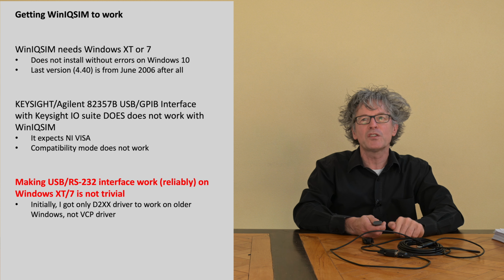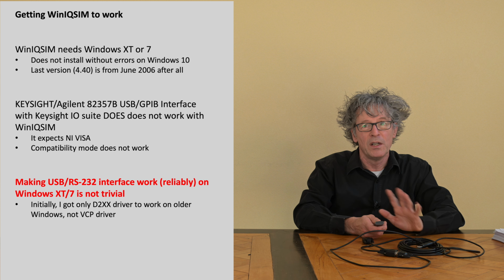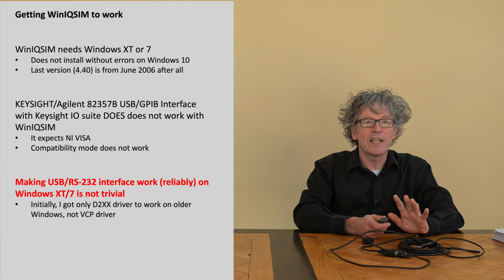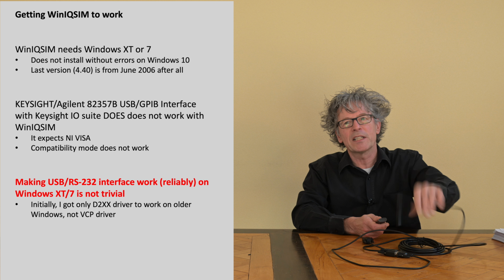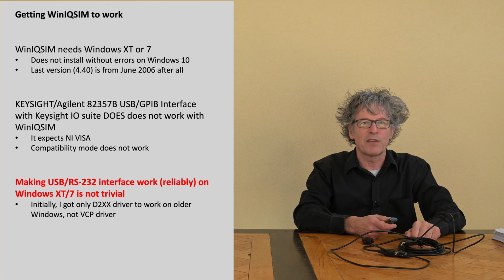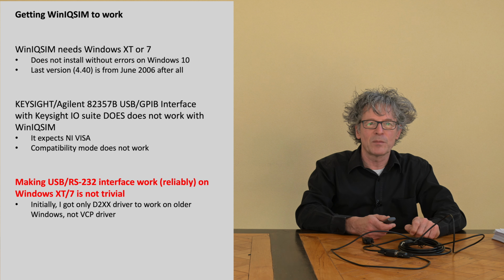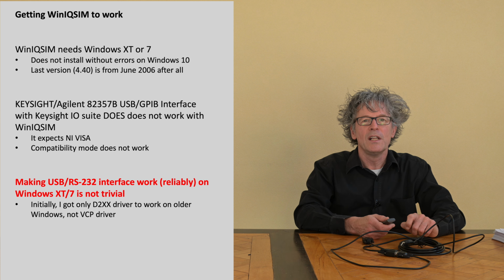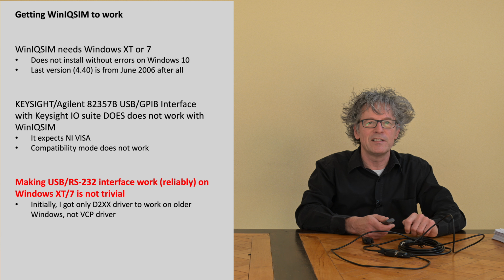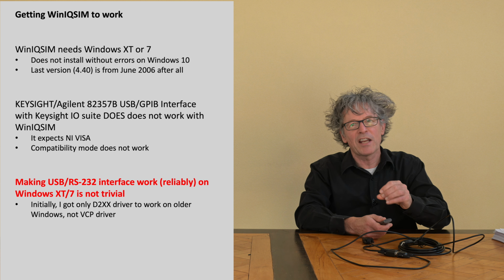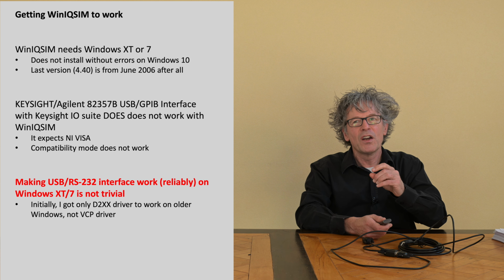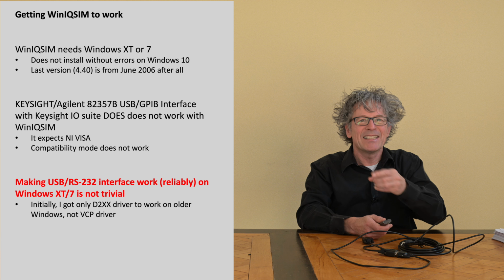It's easy to do on a recent operating system, but I had to get back to Windows XP, and the Windows XP support basically was not available by the maker of this cable, but in the end I figured out what chipset is there, and I found in some old archives some chipset drivers from the early 2000s or so. But note there are two different drivers. There's the D2XX drivers and there's the VCP driver. And initially I only managed to get the D2XX driver to work, which is nice to have, but it's not generating a COM port, a serial port, and it's the COM port that you need.